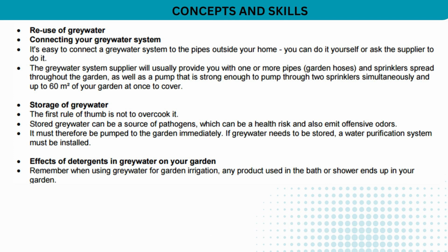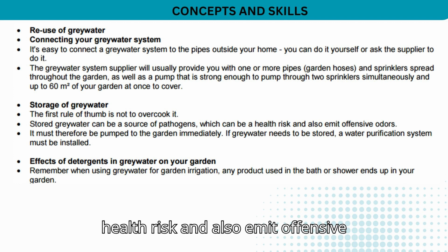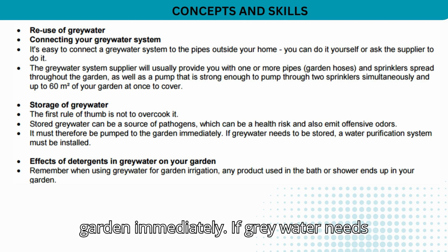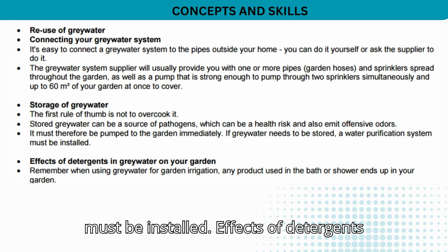Storage of grey water. The first rule of thumb is not to store it. Stored grey water can be a source of pathogens, which can be a health risk and also emit offensive odors. It must therefore be pumped to the garden immediately. If grey water needs to be stored, a water purification system must be installed.